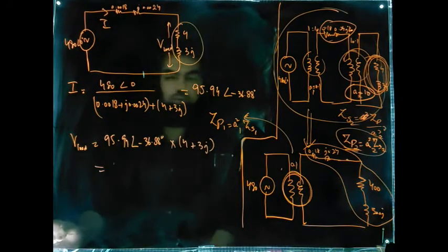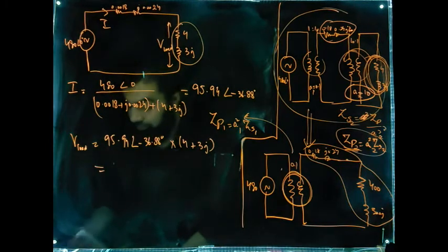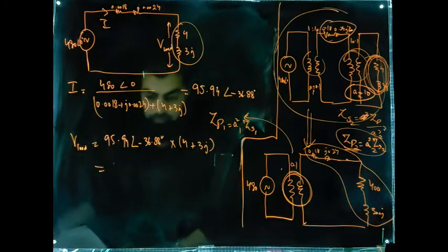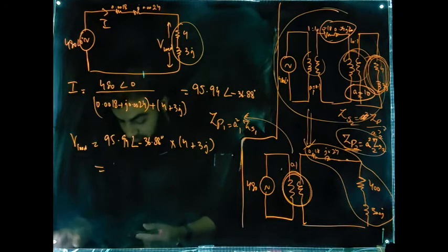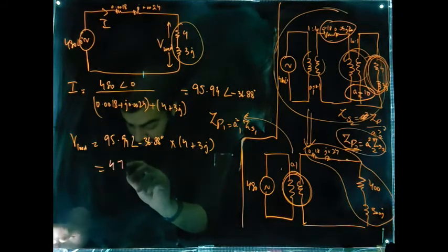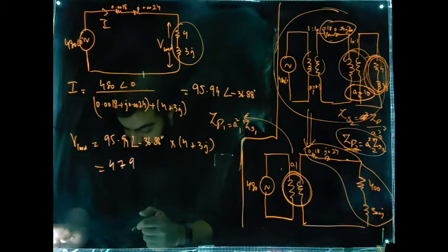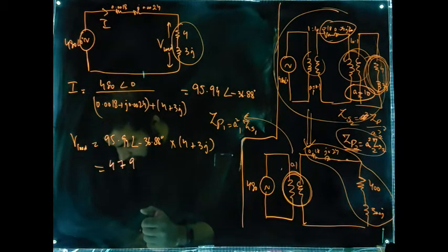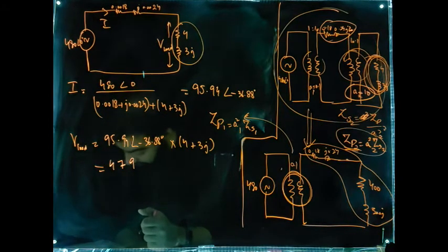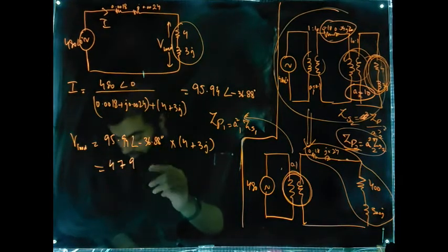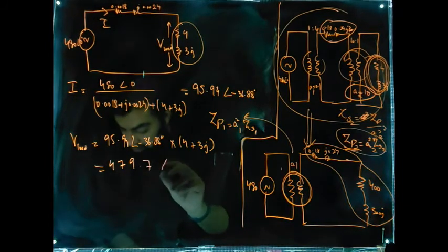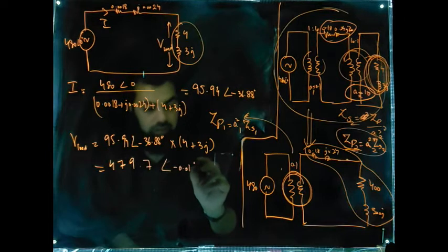So this load voltage, the output voltage, will therefore be equal to 479.7 angle minus 0.01 degrees volts.